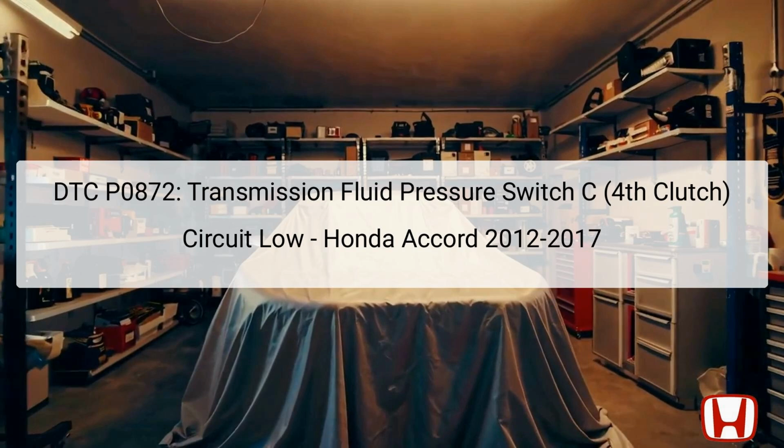between gears. When the system detects a low circuit condition in this switch, the vehicle may default to a fail-safe mode, limiting its transmission operation to either first or fourth gear only. This condition can create significant driving challenges, as shifts into other gears become inaccessible.